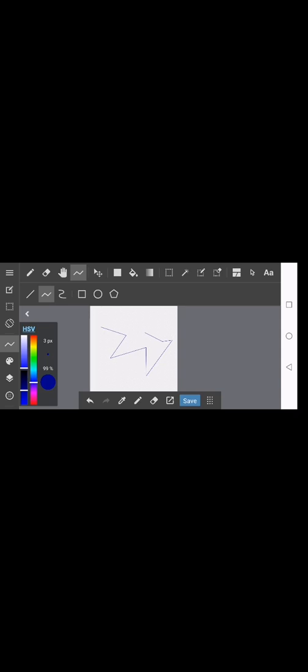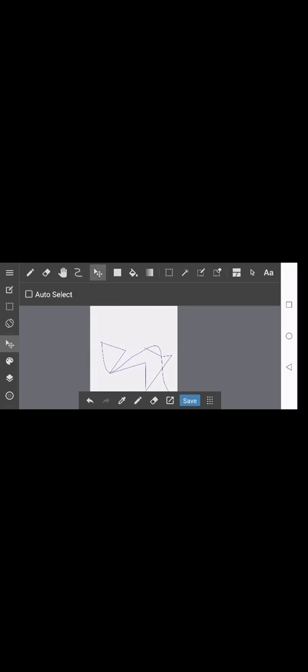If you want to create curves, tap on the first point and the second point, then where you want the curve to go. Then if you're done, tap set. Okay, then this one, simply select your drawing on the current layer and move it around.